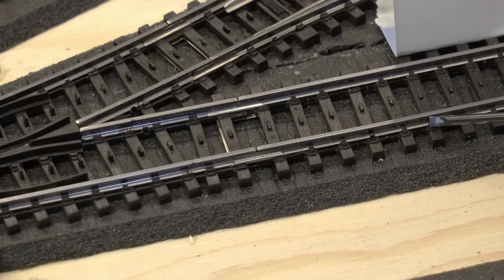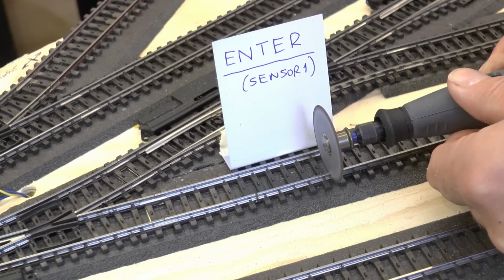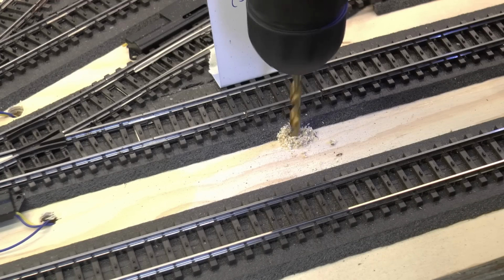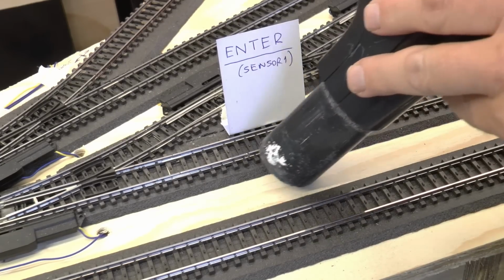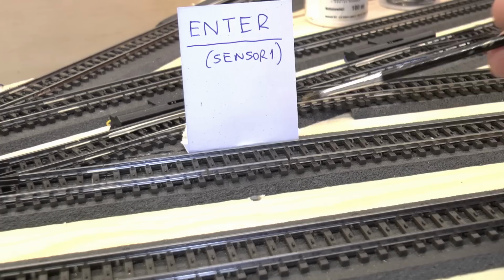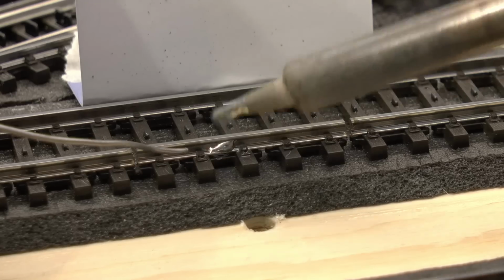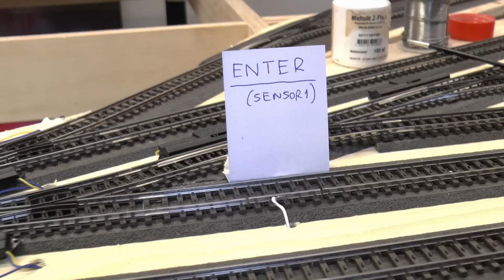I don't want to cut too close to that joint between tracks, so I'm moving 6 sleepers or ties into the next track, and there I start to make my cut. For this I'm using a motor grinder, then I'm drilling the hole for the cable to pass through, vacuuming away any sawdust, adding this special flux for steel and stainless steel, soldering a bead there, and then attaching the cable.